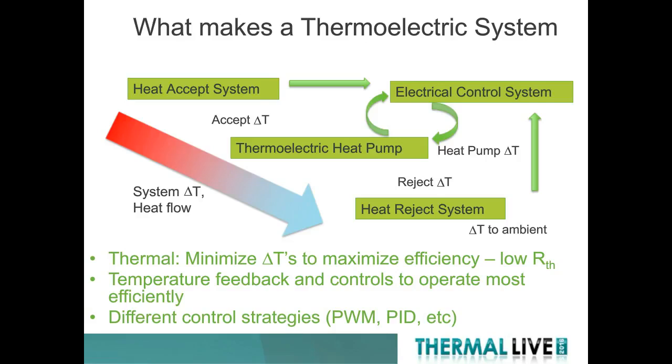It requires all of those working in harmony with each other and taking into account all of the parasitics, all of the losses with respect to not just the thermodynamic system itself, but how that system is controlled to confirm that it is operating within the targeted COP band, while still being able to provide all of the capacity needed for that system and to eliminate heat leak back, particularly in refrigeration applications, when the system is de-energized.